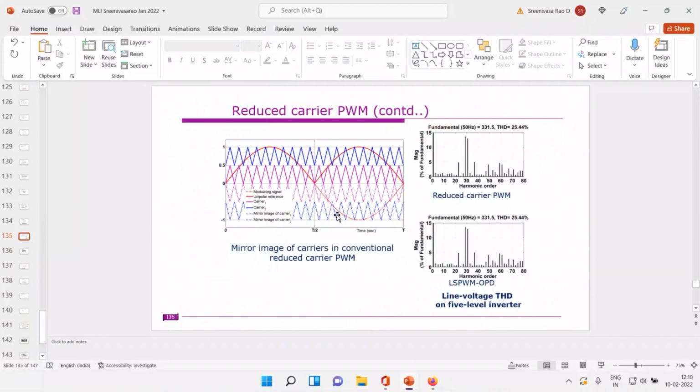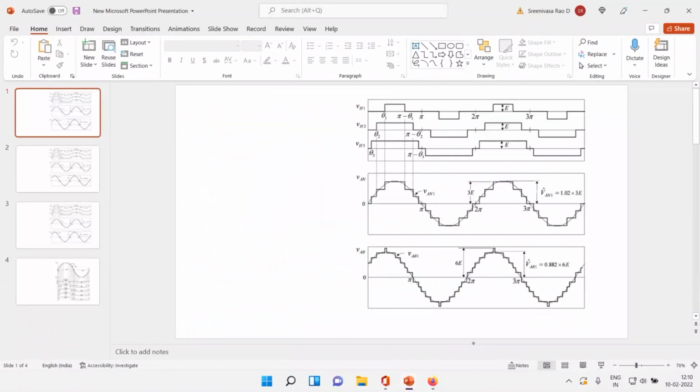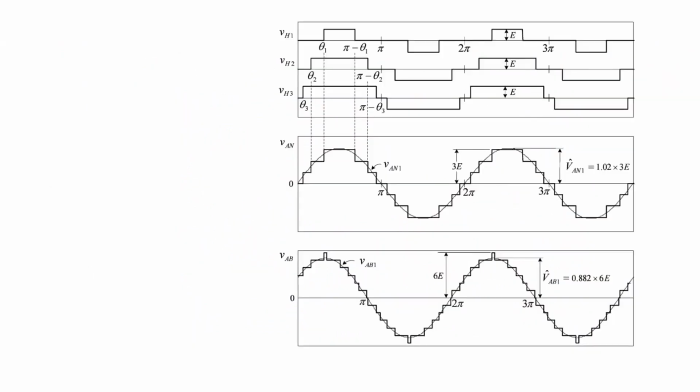So next method. So these are the carrier-based PWM schemes and the digital implementation, especially by using DSpace or by using lookup tables, right? So next we have another modulation, that is the selective harmonic elimination for higher levels.